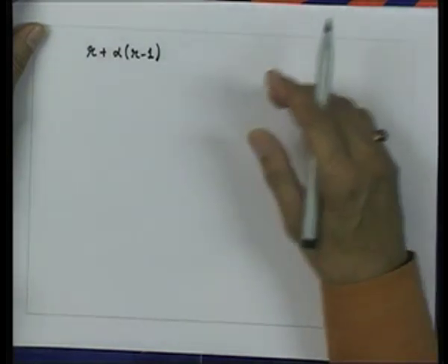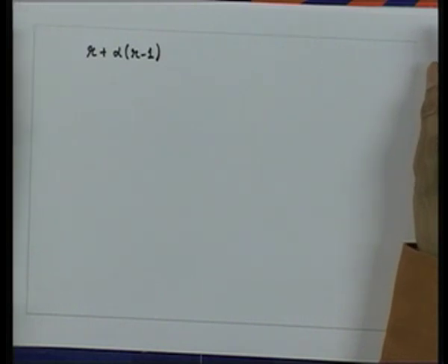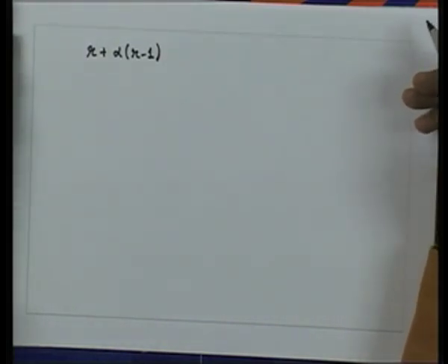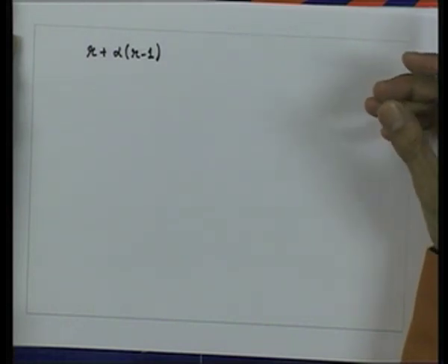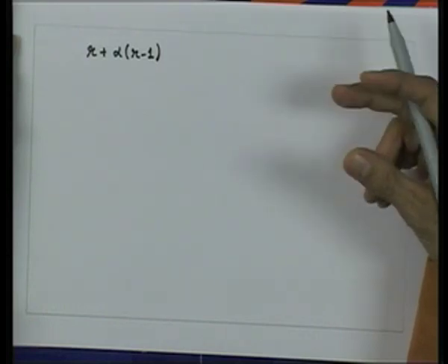Now, the only hitch was that if this condition is not satisfied, then we said that we can add some dummy variables with probability 0 and then combine R symbols at each stage of source reduction, and in the final stage when we are getting the code words for the particular symbols, we ignore the code words for the dummy symbols.